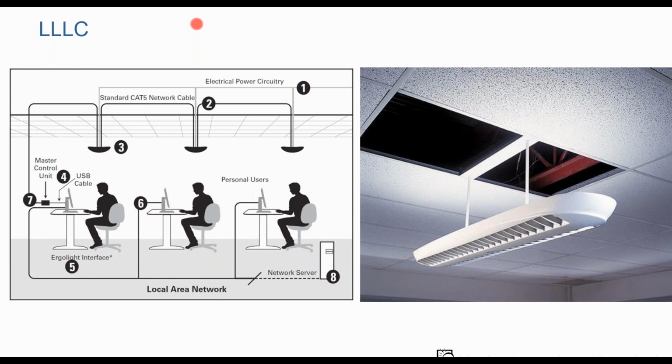Why? Because at the time, luminaire level lighting controls or vertically integrated luminaire systems would have required us to use multiple lighting control systems. We would have had to have one control system for the office lighting and a completely separate lighting control system for all of the rest of the lighting in the building, the downlights, the accent lights, all these other things.